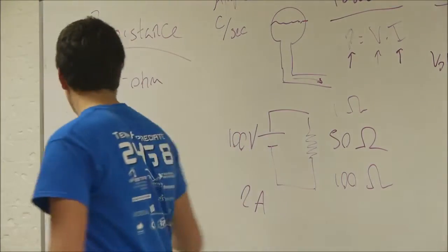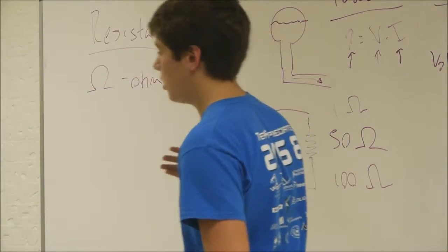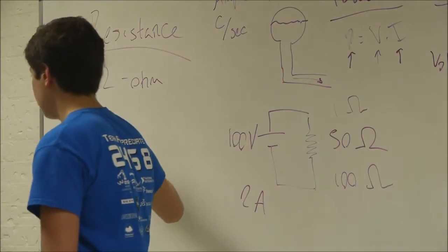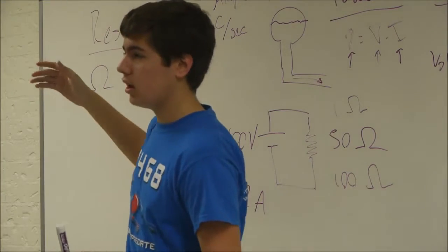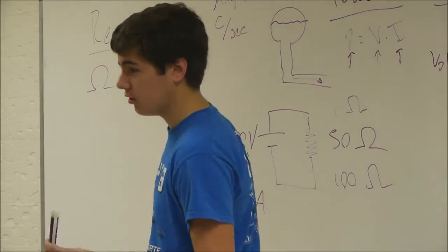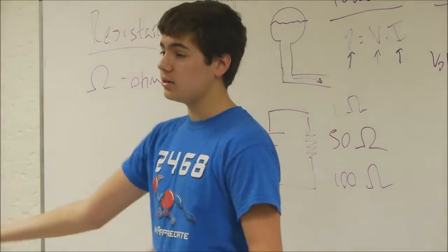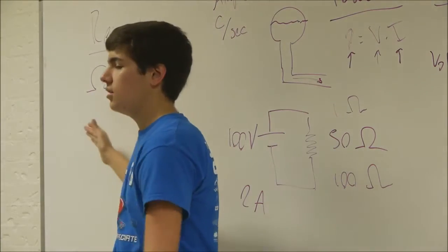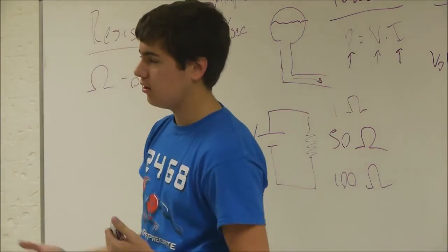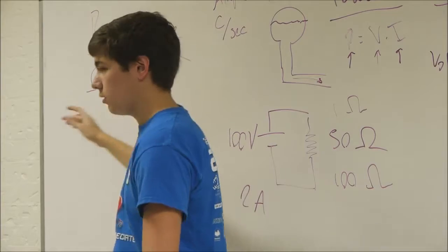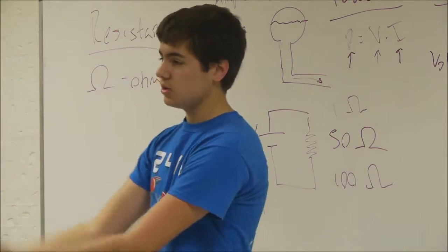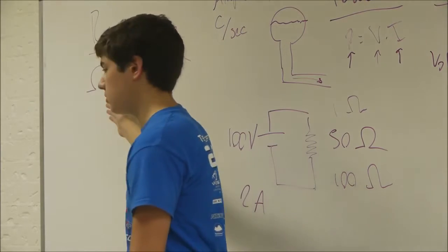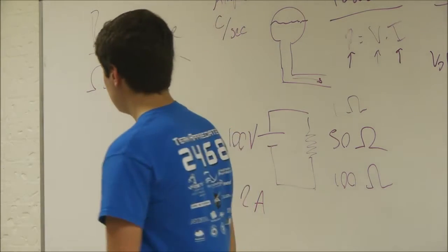it's useful for loads, like we just demonstrated with this. But you have to think about it in a lot of applications. So, for example, when I'm transmitting power across a long distance, even wires that are supposed to be conductors aren't perfect conductors, they have a resistance. And so, as I transmit power through that wire, it actually uses up power in transmission. And so you have to think about resistance in that case.